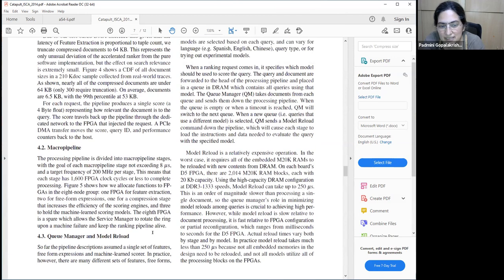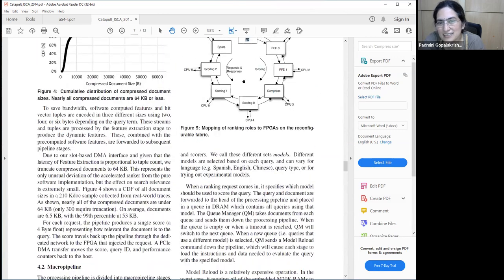So the 8th FPGA is a spare. This is used for redundancy. In case an FPGA comes down, you don't have to take this entire thing down, stop this entire node. You can basically program the spare FPGA while you take down one and replace it or maintain it or whatever.